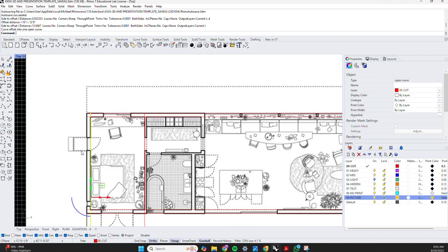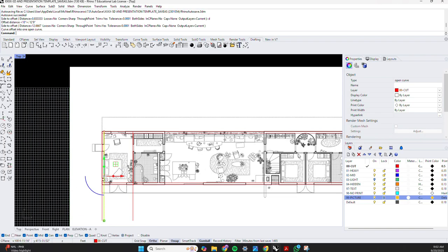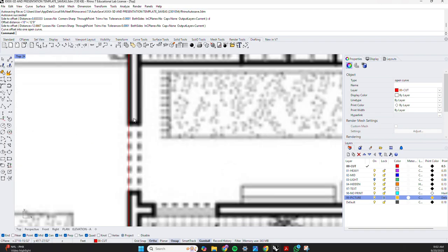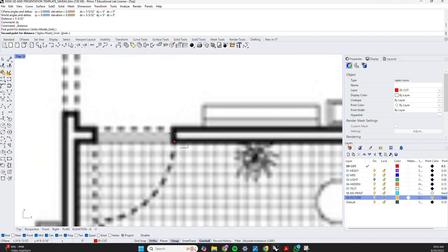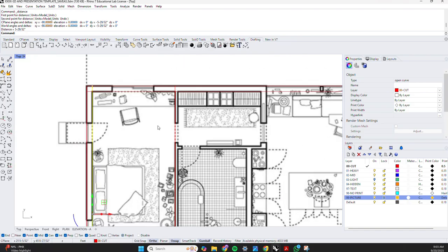How about the depth of this interior wall? Clearly there's this thicker wall that we're calling 10 inches, but it seems like there's also this thinner interior wall that happens at certain points in the project. Let's just do a basic measurement of this. 5 and 5/32. This one is 4. I think for simplicity, and also thinking down the line to making a model of this thing, I'm going to choose 5 inches.